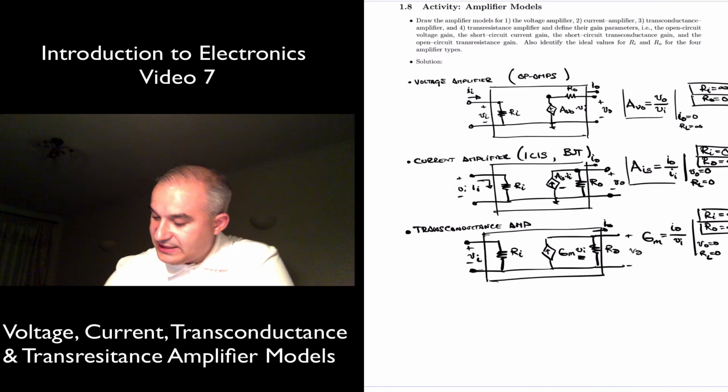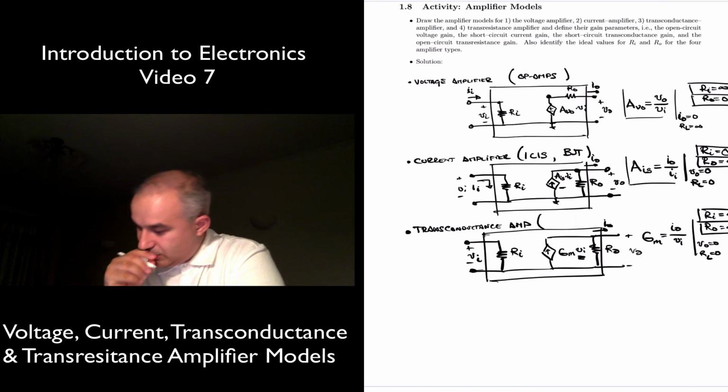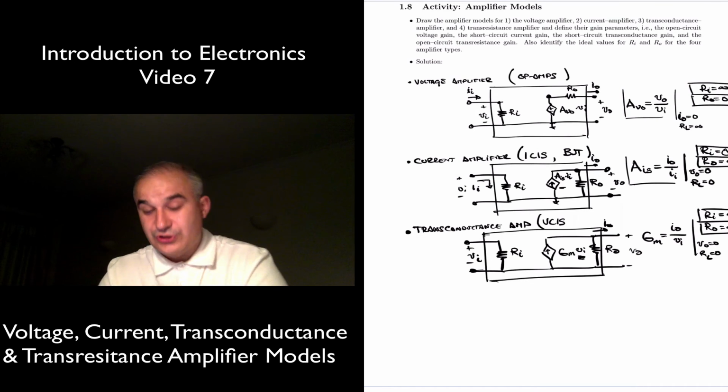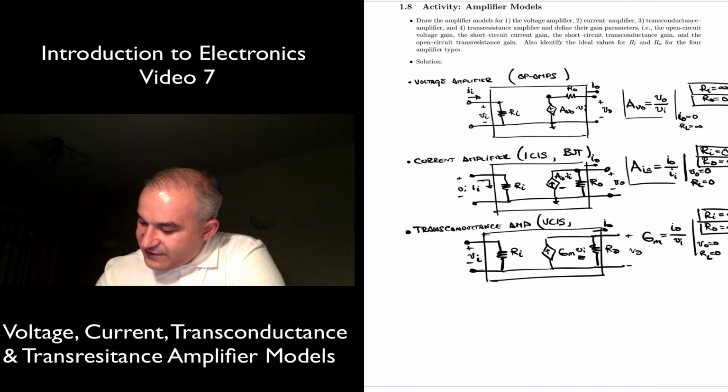Now, you use this to model any voltage controlled current source amplifier, but it is also a good model for BJTs as well as for MOSFETs.